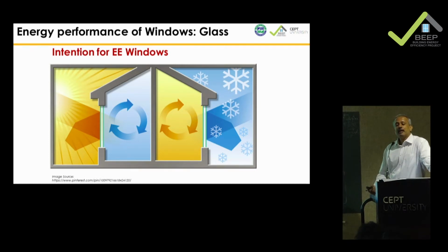And the same thing applies in your windows, in your walls and roofs as well. When you say, oh, the U value of the wall with a 50 mm cavity is X, it will not be the same for a roof. Because the convective current within the cavity will really change the performance of the two. It will start transferring more heat when it is horizontal.